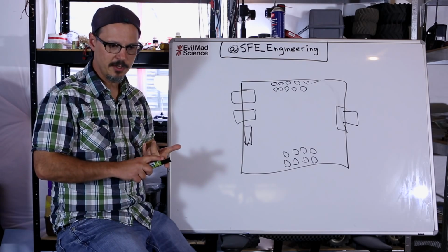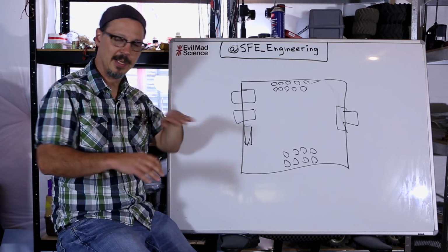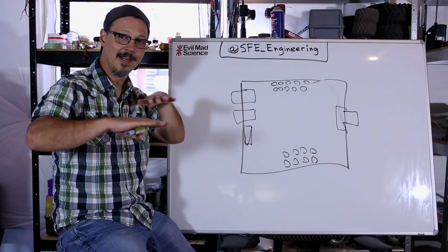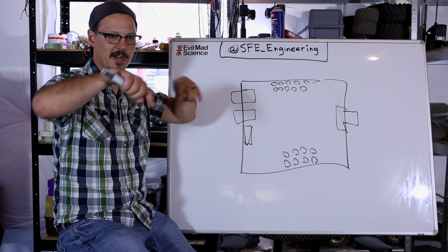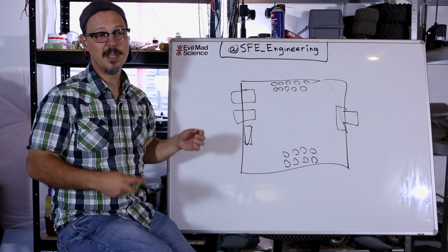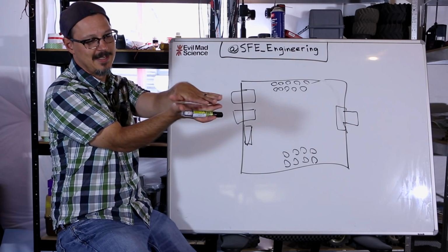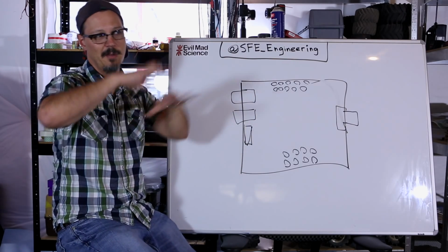What a 4-layer will get you is potentially a dedicated VCC plane in the middle and a dedicated ground plane in the middle. And that's a cool thing because you never have to worry about stringing weird traces places to get things done like you do with a 2-layer board. You also get the additional capacitance between the 2 layers, so it'll act as a little bit of a filter, right? So you're decoupling everywhere.